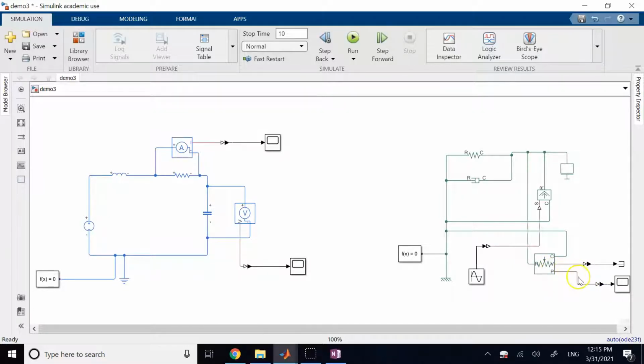So here I connect P to a scope, but again, I cannot directly go from position P to the scope block. Why? Because now I'm doing backwards. I'm going from a physical signal to a Simulink block. So in order to go backwards now from physical system to Simulink block, I need this intermediate block, which is called what?